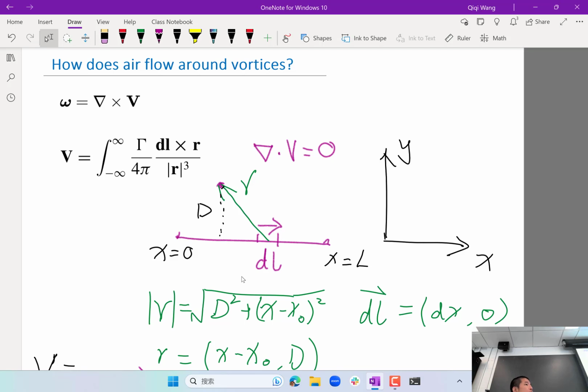These two pieces of information uniquely determine a three-dimensional flow field. So although the vorticity has 3 components, we know that vorticity by definition has 0 divergence, right? So the 0 divergence criterion actually removes 1 degree of freedom from the 3-dimensional vector field.